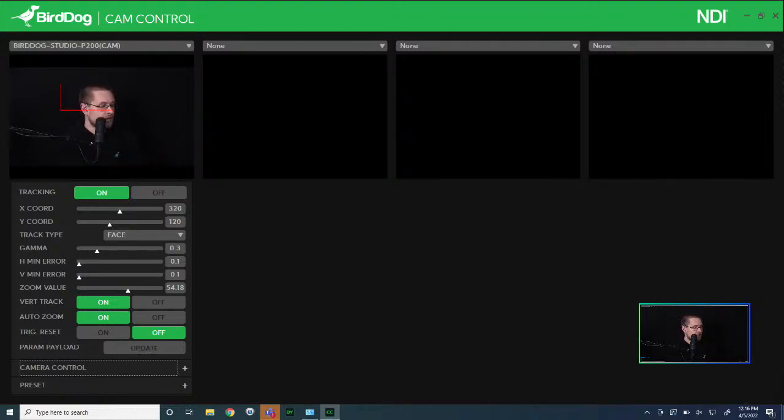All right, so I like 120. Let's see how that kind of behaves here. Maybe a little bit more just to get this to align correctly. So maybe 110, 114. Sure, why not? All right, I'm where my eyes need to be in this shot. Now we turn on vertical error correction. Okay, 02. And the horizontal correction, 03. We hit update on that. And now, when I move, it moves when I pass those thresholds.